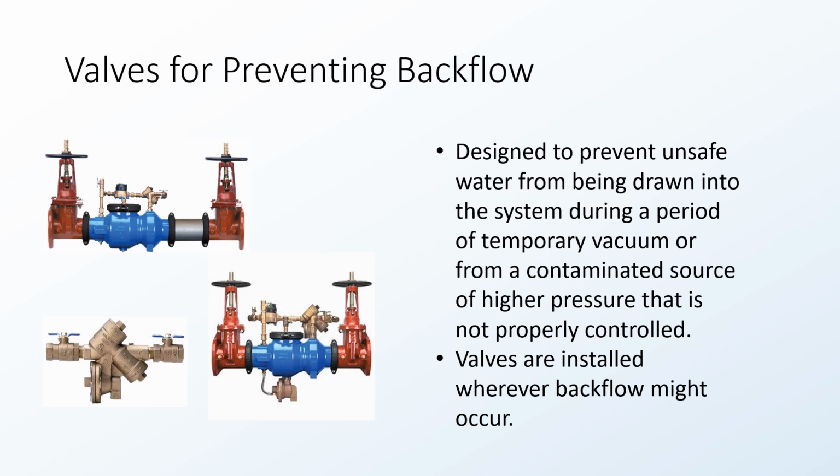I know recently the cross connection control handbook was updated, requiring every single fire service to have one of these installed. In the past, they were able to get by with just what they call a PIV, or post indicator valve. But now that handbook has come out and stated that they have 10 years to get their RPDAs installed or DCDAs, depending on which one your system requires.